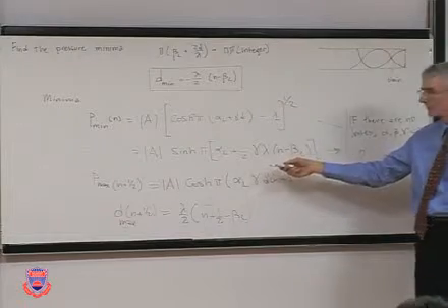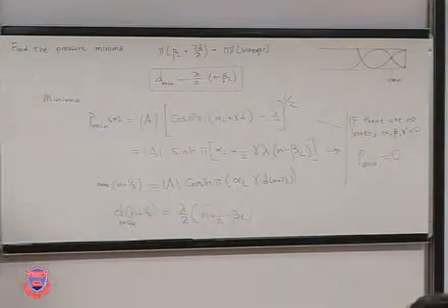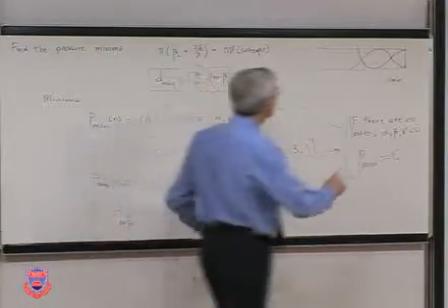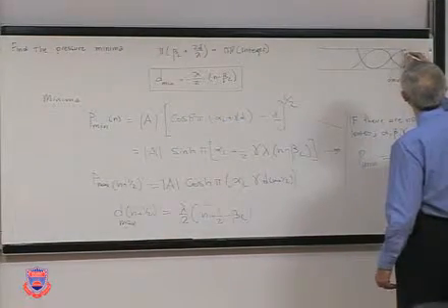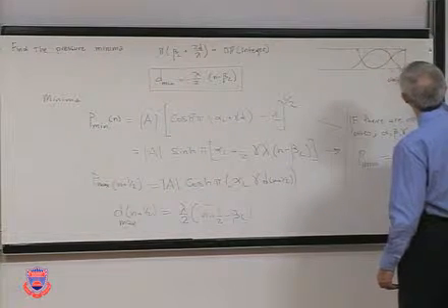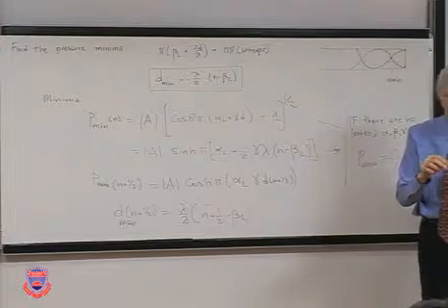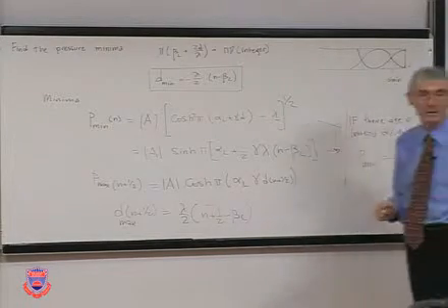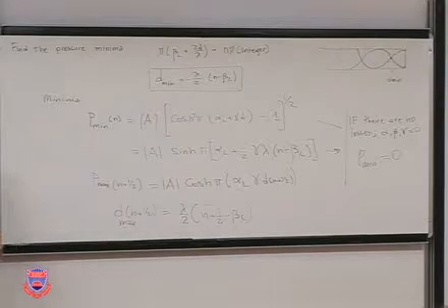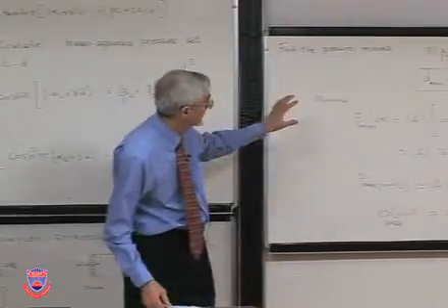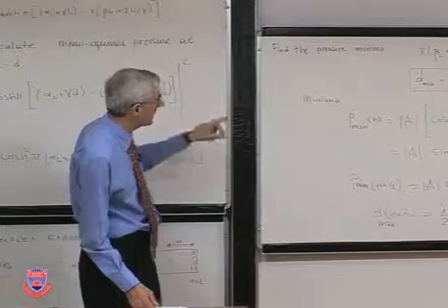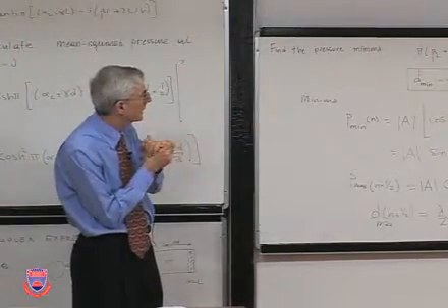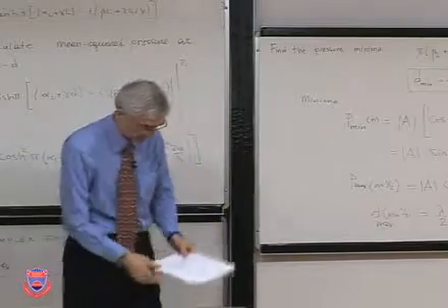In this case, however, okay, I will use a little red pen. In this case, sound pressure does not really reach a zero value. There is always an amplitude at the minimum because of the losses. Okay, that's the big difference here. And this complex mathematics approach actually is very helpful in terms of finding out the relationships for minima and maxima. But now I'm going to write a little prescription as to how you measure them. Okay?